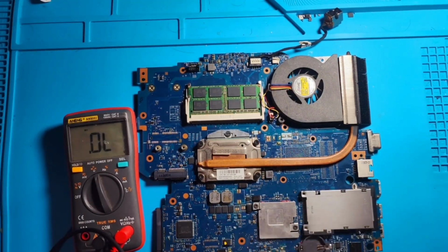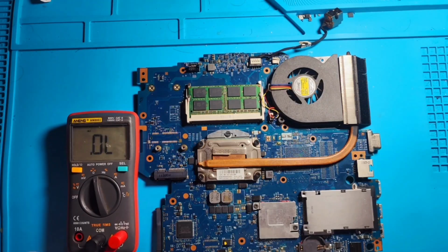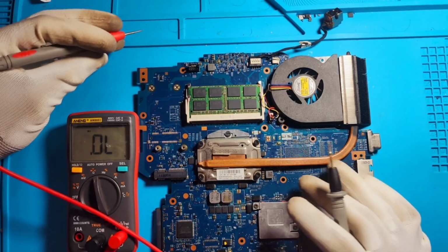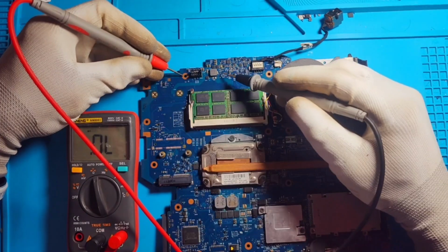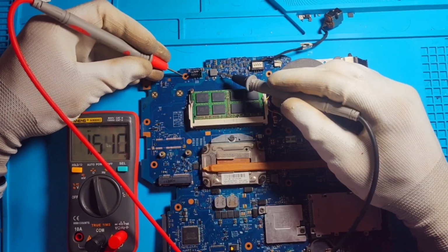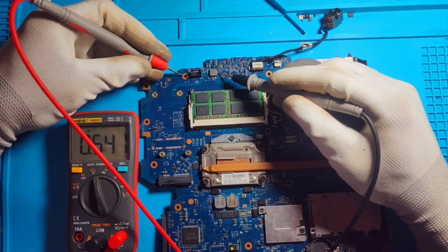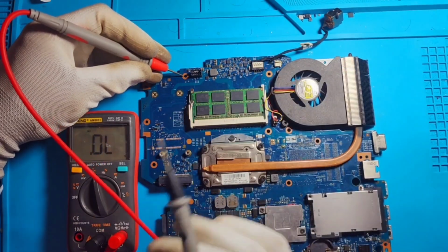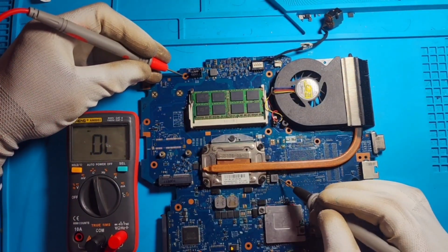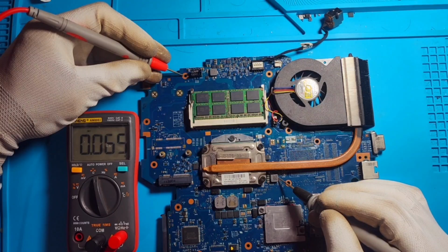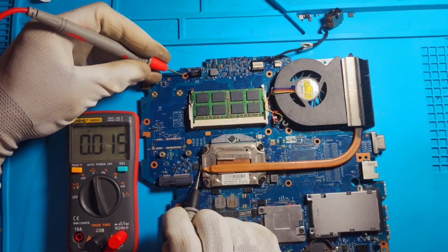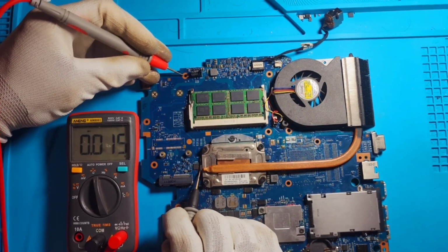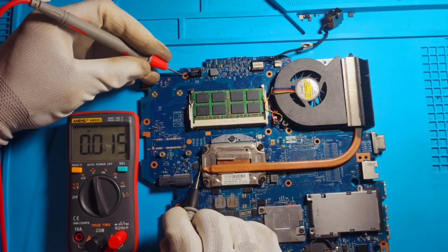Now we are going to check with regard to ground. So I am going to shift the probes. Now positive probe back to ground, and the negative probe on the coils in order to check the lower MOSFET. So 541, 65, okay, 15, actually it is 0.015.